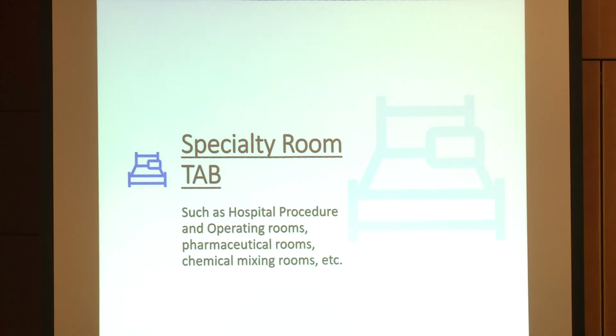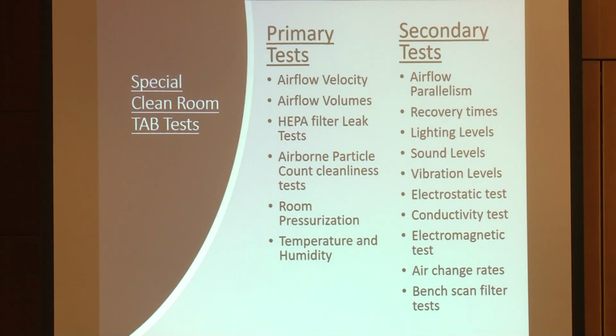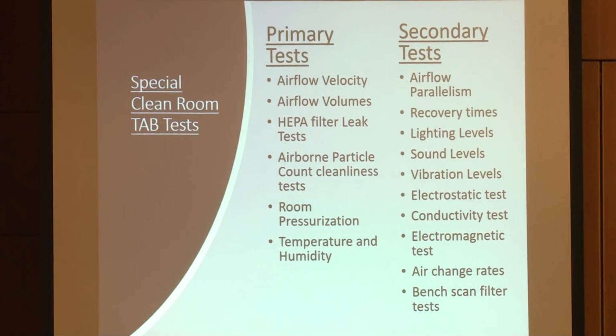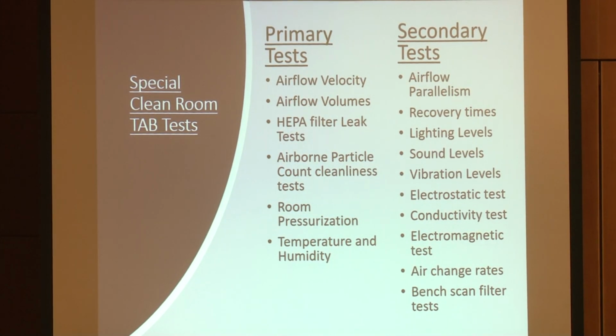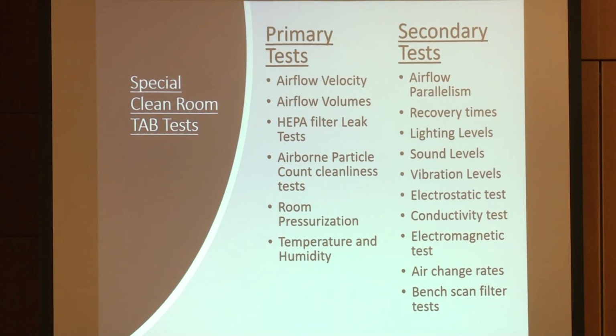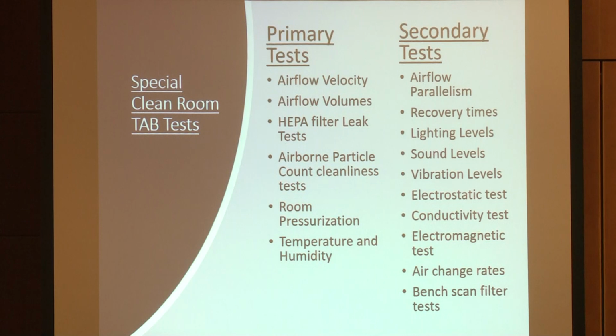Now, normally on HVAC&R systems in normal buildings like classrooms or schools or hospitals or whatever, we just do the normal everyday units. But sometimes, like in commissioning, we have to go and do specialty rooms, like hospital rooms, data centers and laboratories, pharma, clean rooms, that sort of thing. We talked about this as far as the commissioning, but most of the commissioning work in a clean room is done by the TAB professional. And so I just want to go through briefly what that TAB professional has to do.